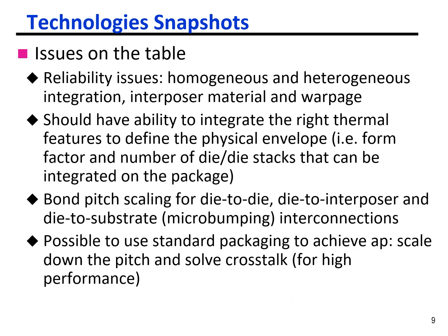So basically, here we show some issues on the table. We include the reliability issue, and also we should have the ability to integrate the right thermal feature to define the physical envelope, and we need to have the bump pitch scaling for the die-to-die, die-to-interposer, and die-to-substrate interconnections. So in order to have the benefits from the advanced packaging.